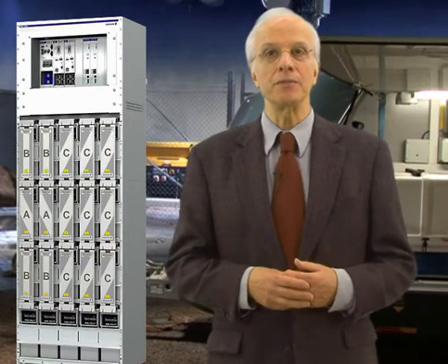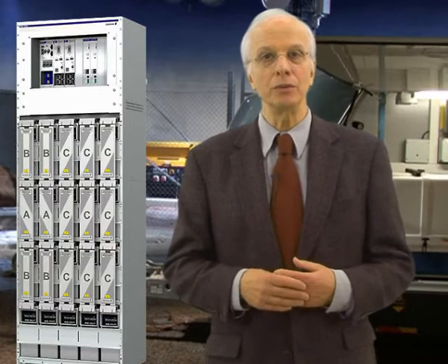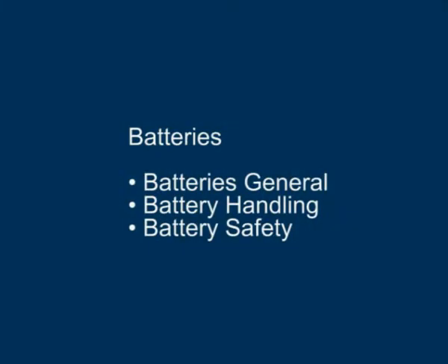The battery is connected to a battery connection unit that functions like a switch or fuse in case of failure in the system. This unit can also disconnect the batteries if the voltage level drops too low to prevent them from being discharged to a lower limit than allowed. If you wish to know more about batteries and how they're handled, all you need to do is to refer to the separate film clips about batteries.